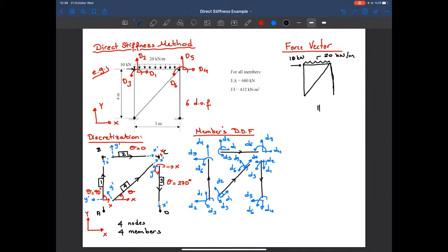We are saying that that's equal to the no deformation case. We are fixing all the member ends. Let me show it this way. I fix all the member ends, so all the nodal degrees of freedom are equal to 0. And we have only one member load, and due to the member load, my fixed end moments and the forces are as follows: 15 kilonewton meter,